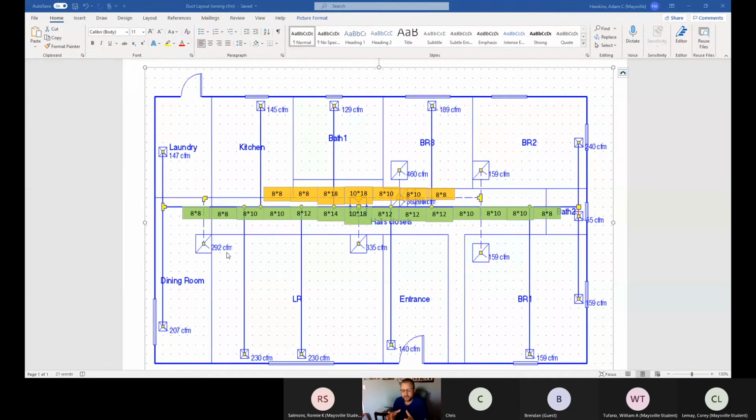That's a weird way to say it, but a tractor tire could have 15 PSI in it, and a bicycle tire could have 15 PSI in it, but obviously one of them has more air than the other. So the pressure needs to remain constant, but the space is going to be bigger if I have to move more air. And so that's a basic guideline for it. And then the return is essentially the same thing. Your return has to be able to carry everything. And once you bring stuff in or take stuff off, it gets smaller.